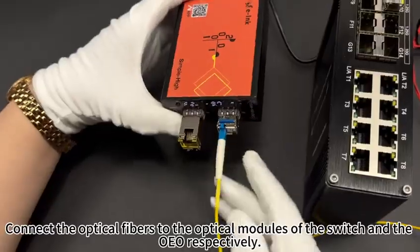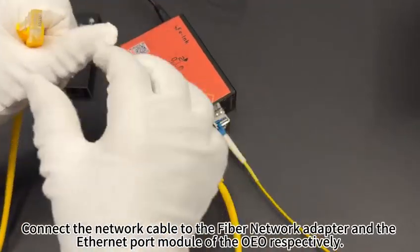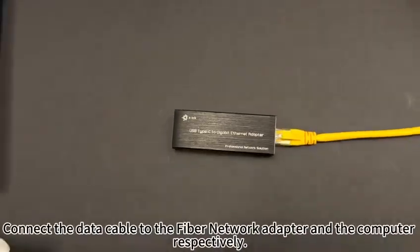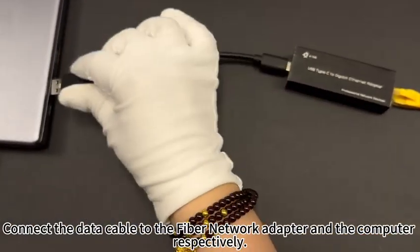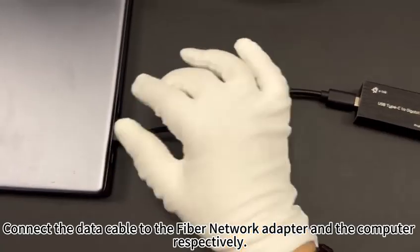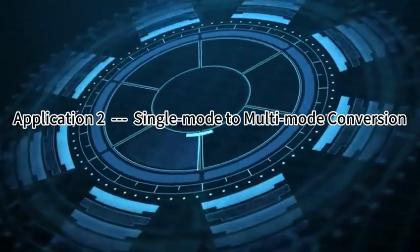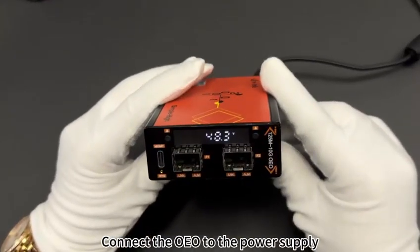Respectively. Connect the network cable to the fiber network adapter and the Ethernet port module of the OEO respectively. Connect the data cable to the fiber network adapter and the computer respectively. Connect the OEO to the power supply.